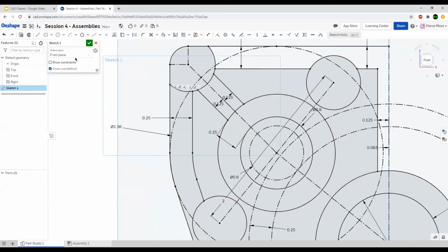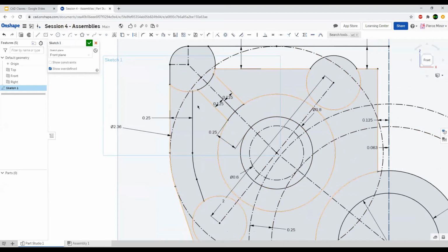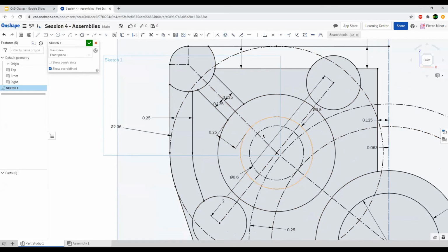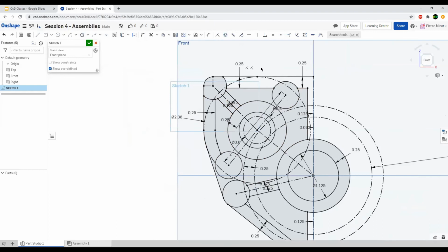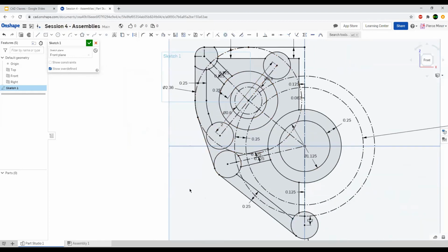A pretty easy way to create a nice rounded corner, or well, actually no, first I'm going to discuss why rounded corners are so good. First of all, yeah, they look super nice, but also if you're trying to create a complex plate like this, chances are you're going to be using a CNC or a mill, and a limitation of a CNC or a mill is that if you're trying to cut a corner, all the corners they make are rounded because they use drill bits that are designed to cut side to side in addition to up and down.